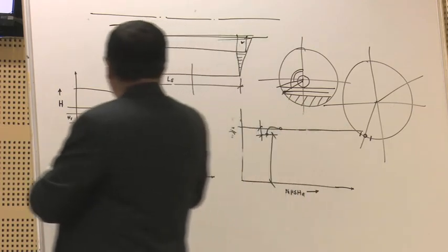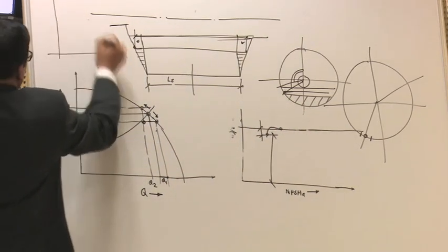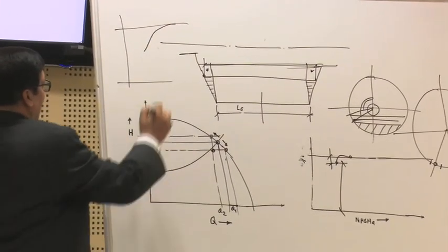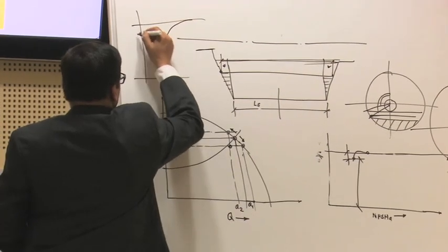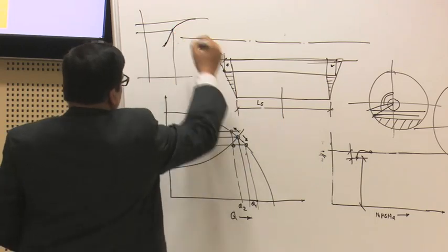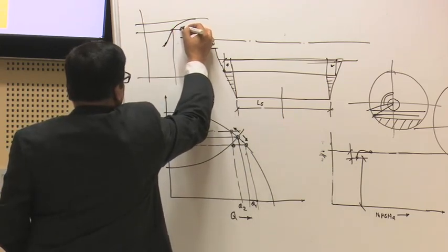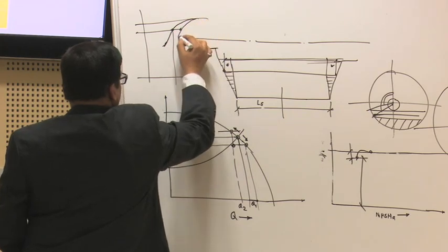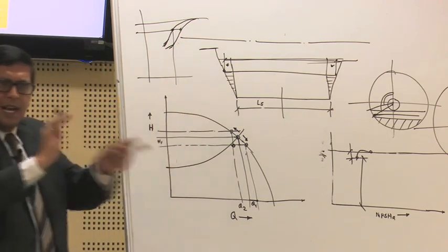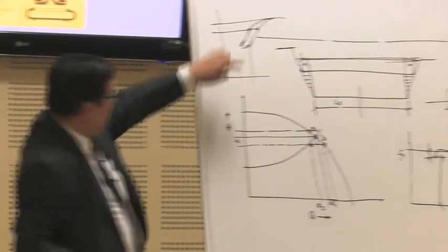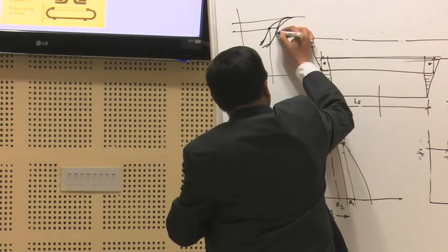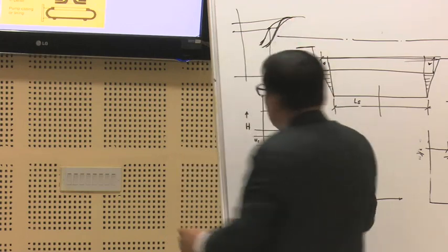You will find that normally, let us say, a cyclone curve should do this, right, under a particular D50 it should do this. Now, because of this pressure fluctuation, it is changing the D50 point, it is doing this. Now the problem is this, these two things are happening at such a short interval that you cannot distinguish between this and that. So industry sees the curve going like this. This is a typical case of UCIL Jadugoda.